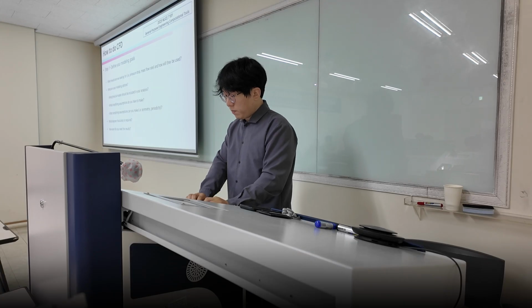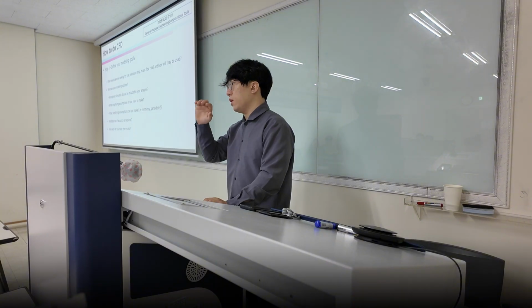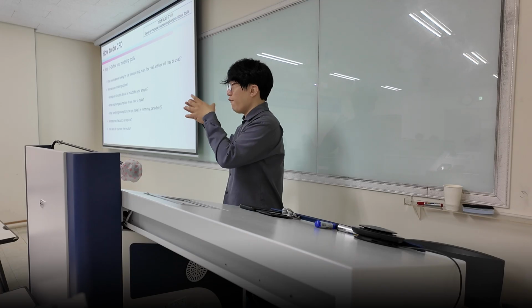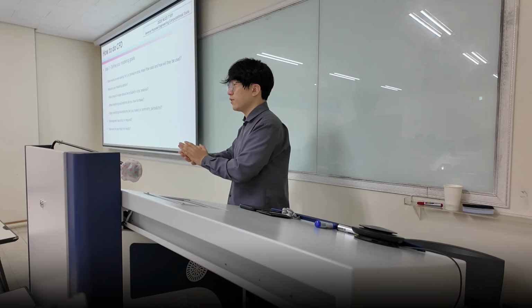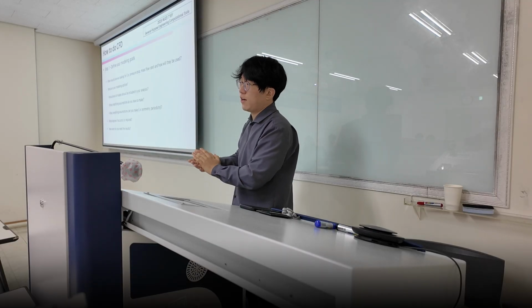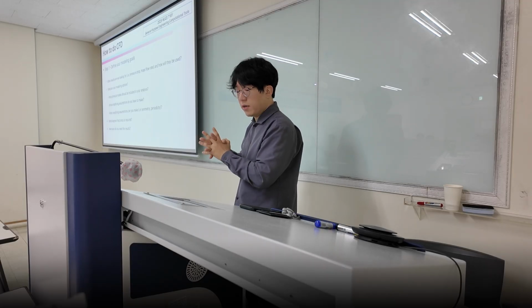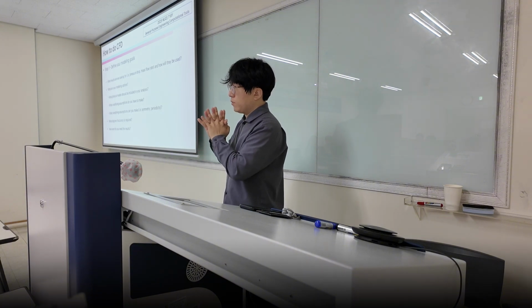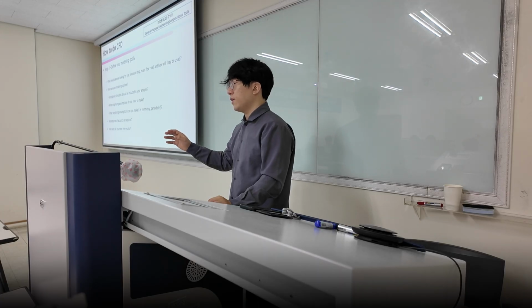So if you're performing a computational dynamics analysis, then make sure you have a ground truth validatable case. Otherwise, what you derive as a solution doesn't really mean much. You can't really prove that the solution is meaningful to other people. So that's one thing. And also, once you perform these numerical experiments, make sure you change the number of mesh and then perform the mesh independence analysis.